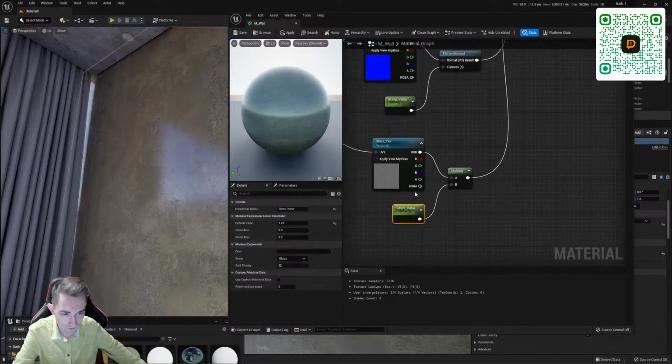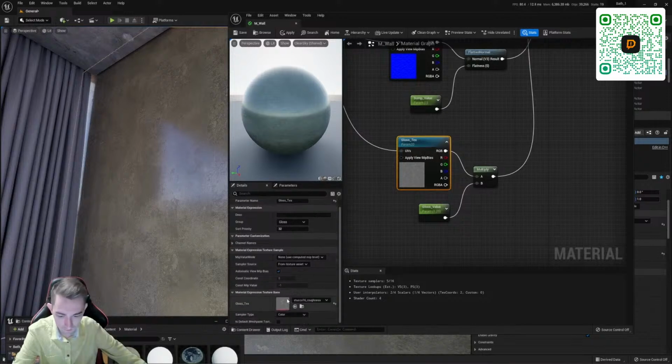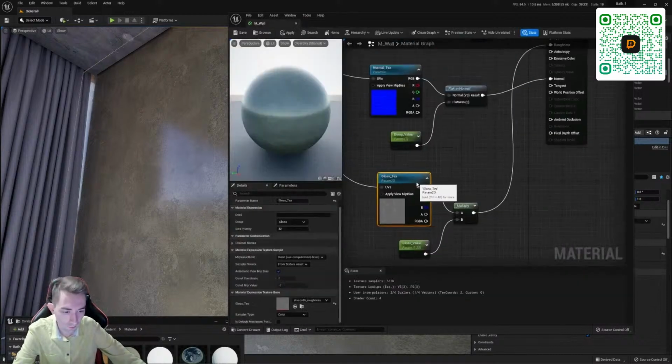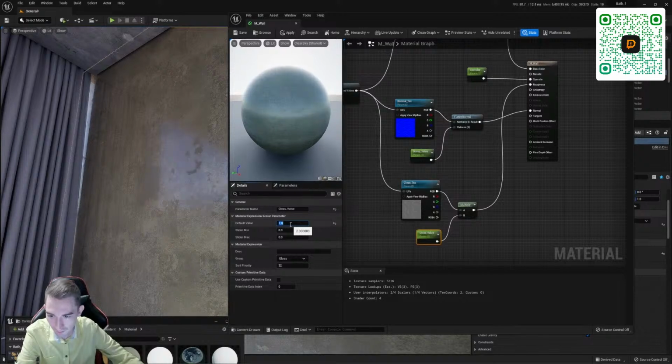I have already told you how to create it. And texture. The texture I have here is like this. I took it from the internet, that is, I found a decorative plaster material, and applied its texture and mixed it with the parameter. Here we multiply its power, I'll put 1.2 from it now, and now we see already somewhere rough, somewhere less rough. I set a small value, you can put it like this even.